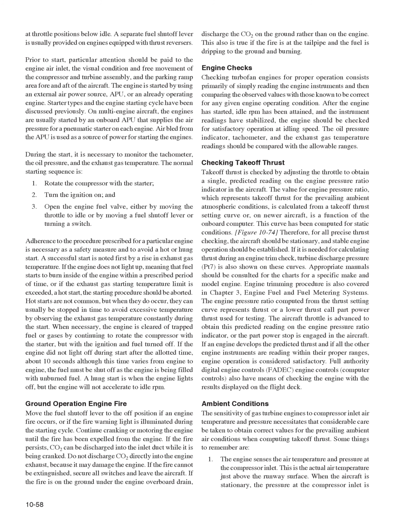If the fire is on the ground under the engine overboard drain, discharge the CO2 on the ground rather than on the engine. This also is true if the fire is at the tailpipe and the fuel is dripping to the ground and burning. Engine checks.